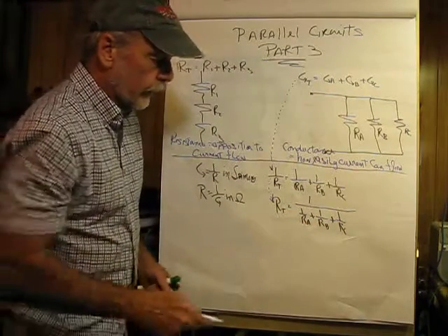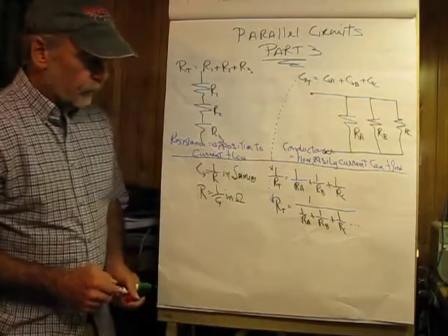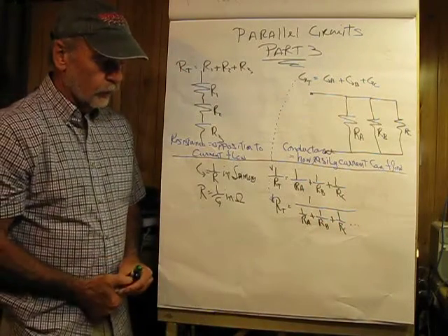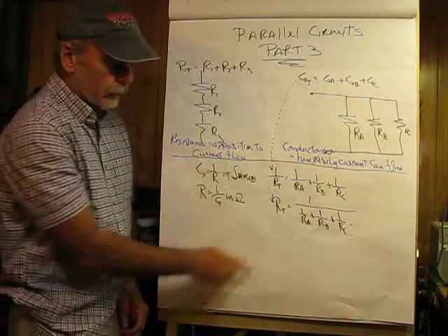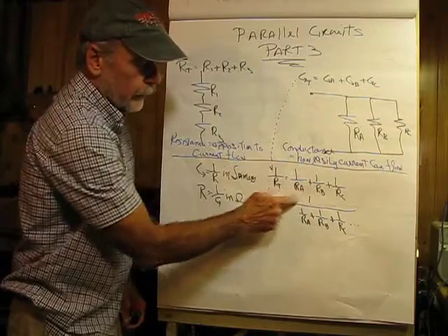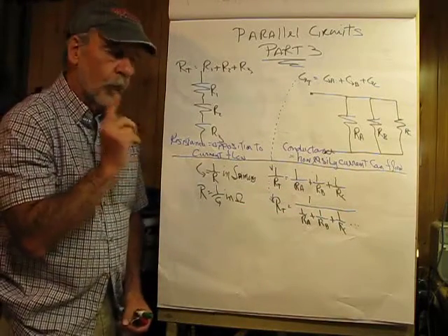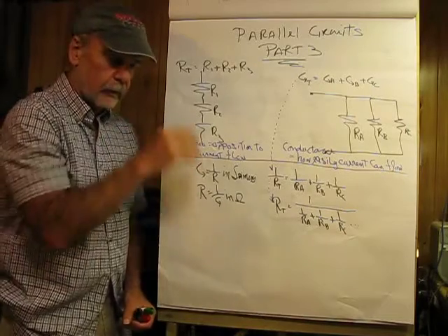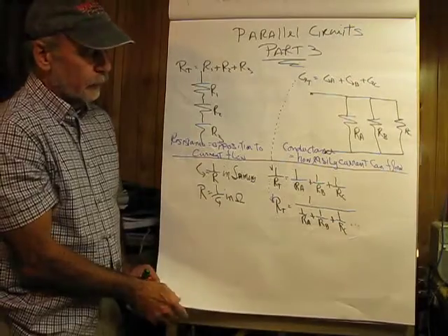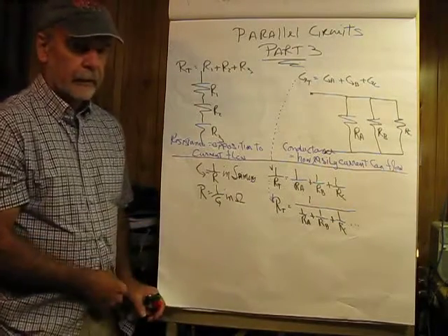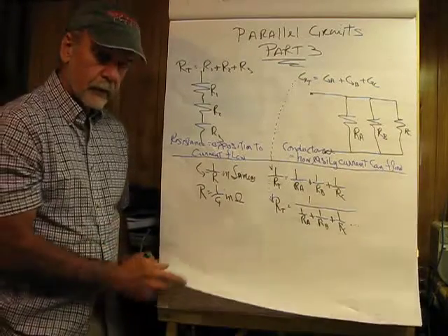And with regard to that, we could keep going. So it's a robust way of finding the total resistance, and kind of problematic, but if you're good at a calculator, you can enter this whole thing on one line using the -1 key. That's raised to the -1 power. So that's kind of our background here, and when I flip this page, what we're going to be looking at is the conductance equivalent to capacitors and inductors.